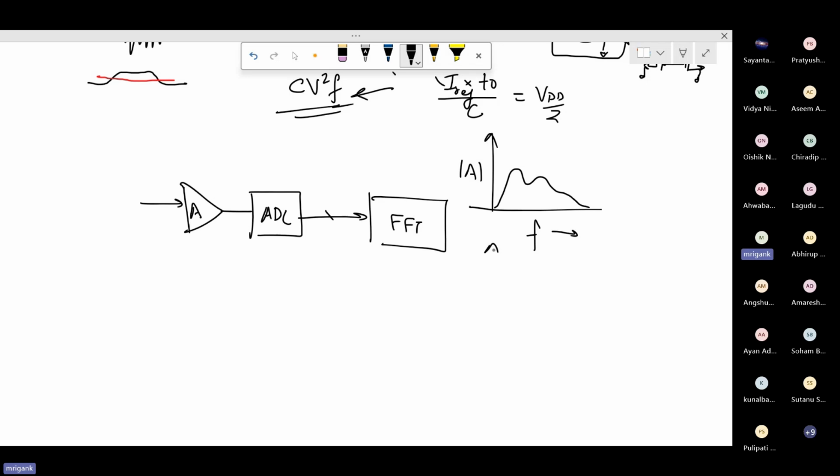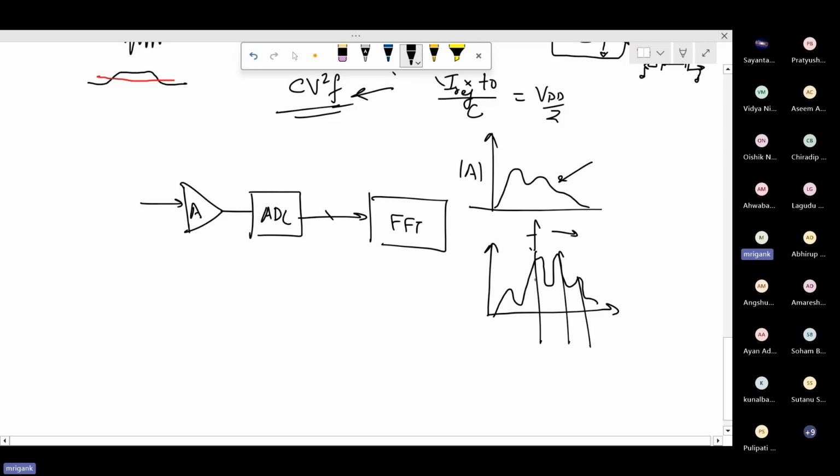And then when the seizure appears, it has certain frequency components. So they will try to see in which bands your frequency is peaking. Suppose in the normal condition it is a normal signal, but when the seizure is coming, it shows some peak at certain frequency bands. So we will try to detect at what frequency the peak is coming, how the frequency characteristics are changing. That is another way, and people claim that it is more accurate, because it is not relying only on the time domain signal, but on the frequency content of the signal. So it will be less sensitive to noise, etc.